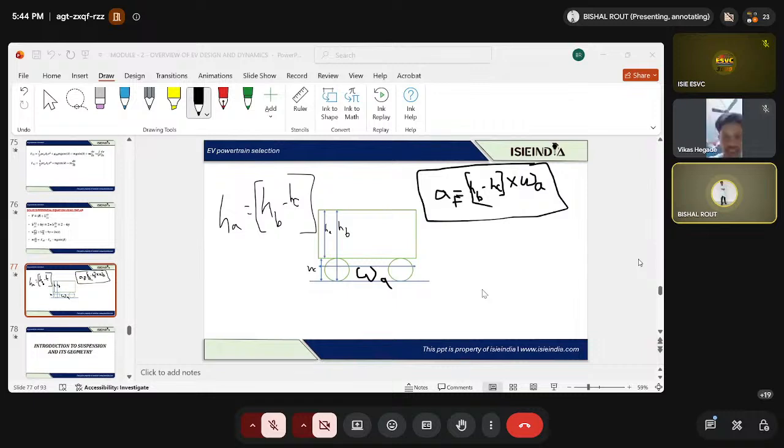This is the steady state speed. Steady state speed means if you apply this much torque, your speed will be steady at 31.11, right? So I will just calculate that particular steady state speed only, so I have to stop the iterations. Sorry for the interruptions, guys. So the steady state speed will be 31.11, in kilometers per hour, which I'm getting, right?